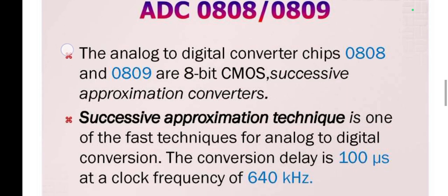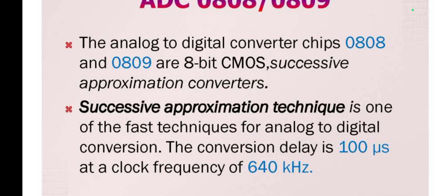Microprocessor sends an initializing signal to the analog to digital converter to start the analog to digital conversion process. The start of conversion signal is a pulse of a specific duration. Two popularly known conversion techniques are successive approximation technique and dual slope integration technique.